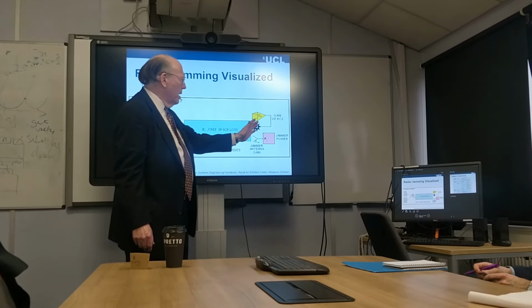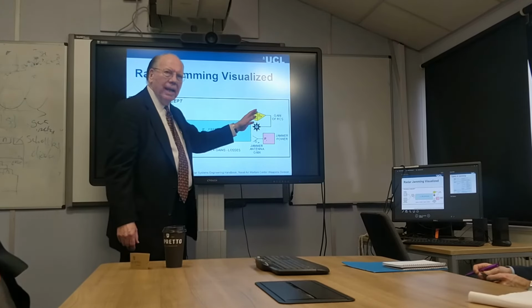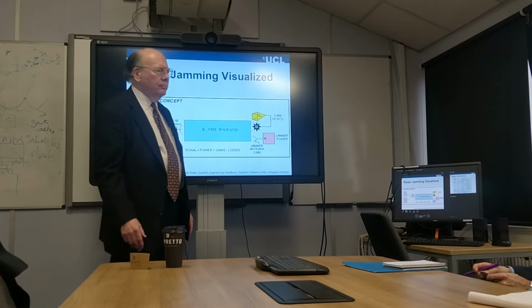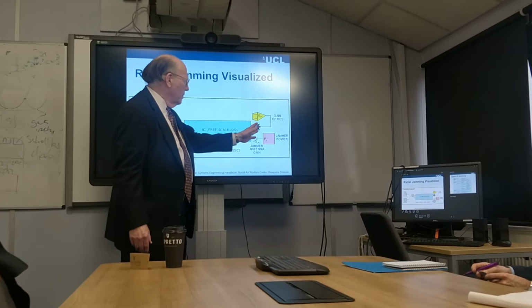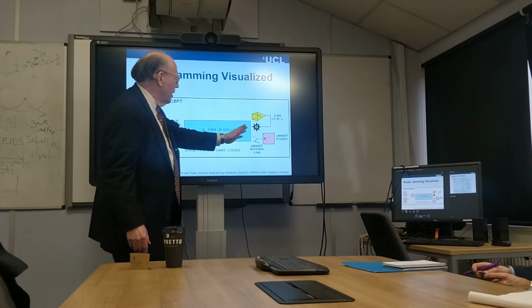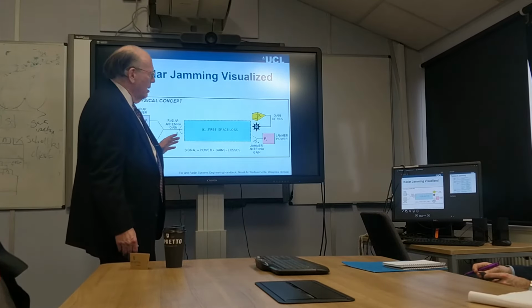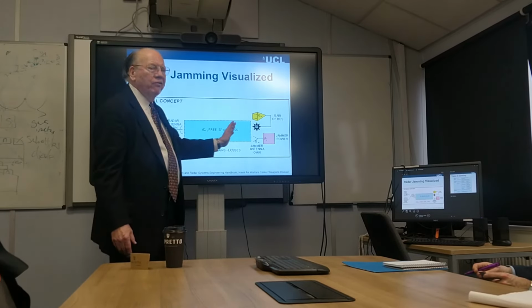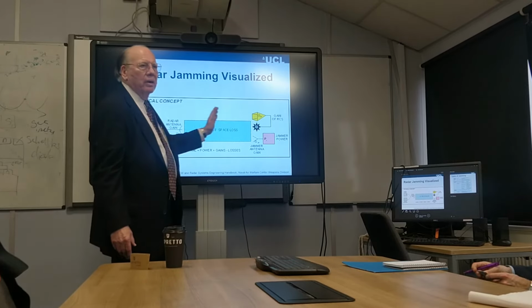It impacts the target, and then the target has a certain gain depending on its radar cross-section, and it re-radiates that energy back to the radar. So the radar signal has experienced an R to the fourth loss, because it's got R squared going out, R squared coming back.